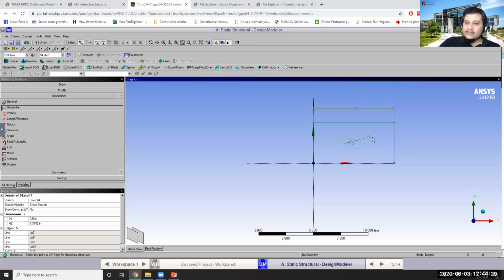Where you are placing this doesn't matter, because these dimensions are not part of your sketch. The sketch is these blue lines. The green lines are not going to be your geometry or part of the sketch. So this distance is supposed to be 10 inches.